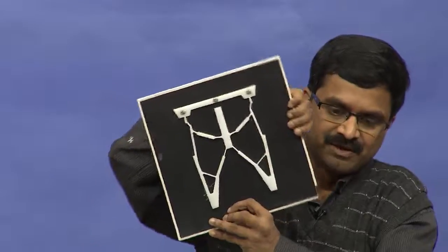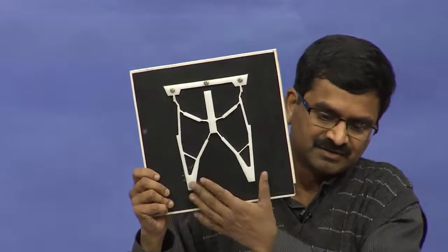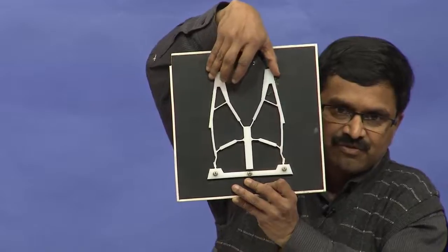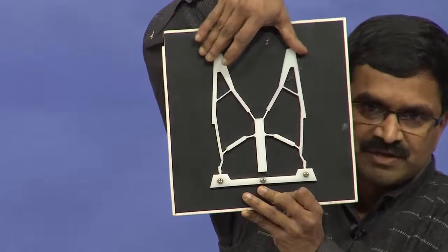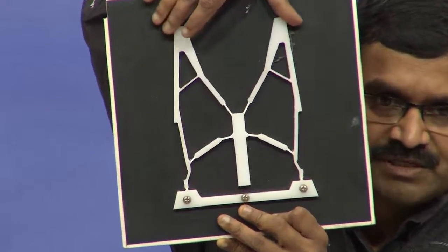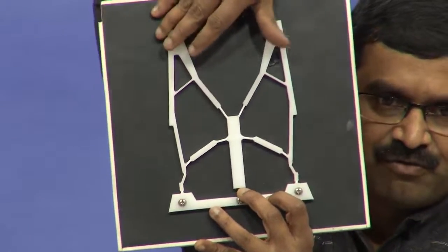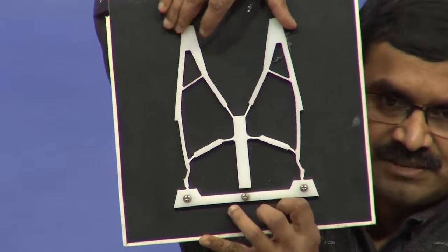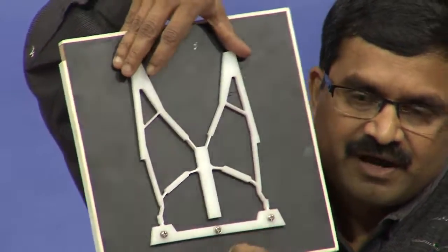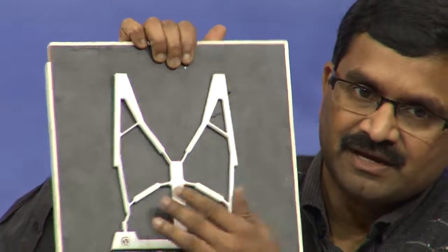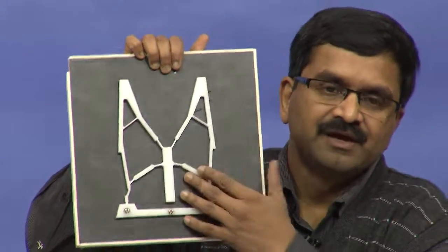as opposed to, let us take the prototype of the other mechanism, which we have to orient. I should put it like this, or upside down. So, this is how it is. With the right hand one, when I apply force, it also seems to be flexible, but a lot more force is required to apply this. And moreover, if I put my finger here and try to feel the force, it does not give as much force. And in fact, if I am not careful here, it will actually go out of plane, because its flexibility in the out of plane direction is more than in plane.